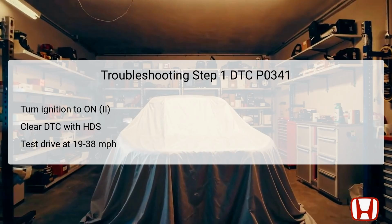Following this, a test drive is necessary to recreate conditions under which the DTC was flagged. Drive the vehicle steadily at a speed range between 19 and 38 miles per hour for a duration of 10 minutes to collect pertinent data. After completing the test drive, it is important to check for any pending or confirmed DTCs with the HDS to see if the P0341 code reappears.